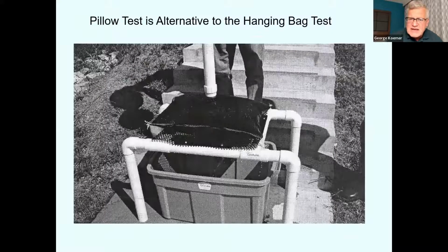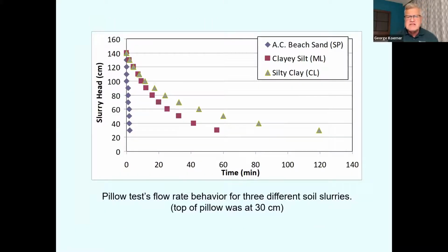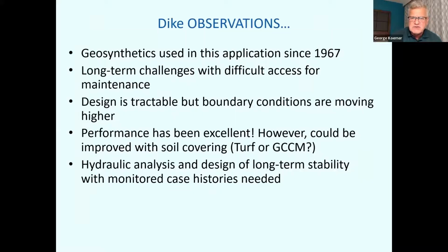In addition to that, you would like to get an idea of how fast the material will dewater. I think we're at the point where we've stopped using the hanging bag test and gone exclusively to pillow tests like this. A fellow by the name of Tom Stevens really championed this work through ASTM, and Chris Timmons as well. The response that you have is the slurry head with respect to time. It's certainly dependent on the marriage between the geotextile in the tube and the infill that you're placing. You have a nice tool to define that. When you get to dredge materials that need to be flocculated or coagulated, you can use flocculants with them and get an idea of performance based on this pillow tube.